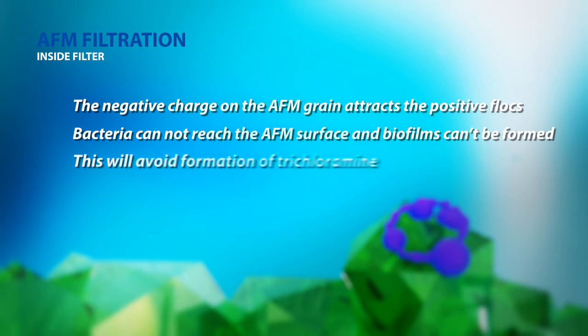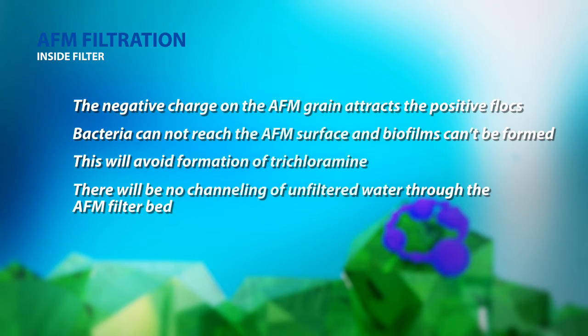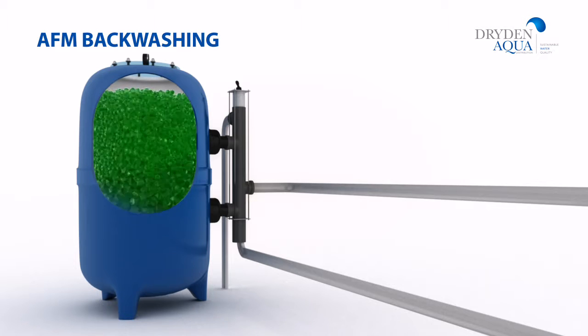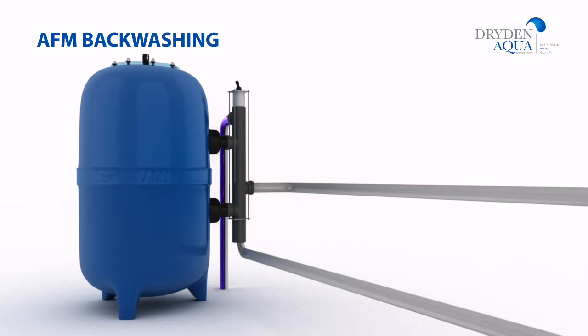AFM is a highly engineered product that provides optimum water filtration. Unlike sand and other filter media, it will not channel, so unfiltered water will never enter the pool. AFM removes much more from the water than sand or any other type of filter media, but what goes in also needs to get out of the filter. This is why filters need to be backwashed with water.